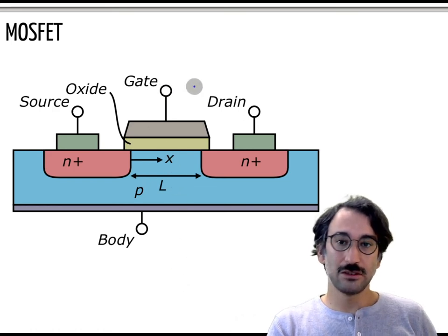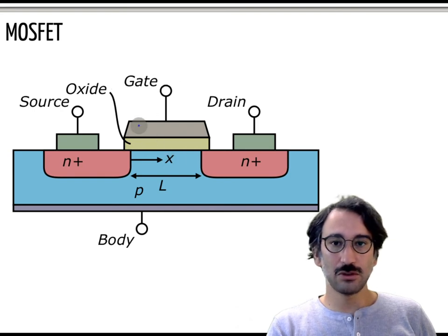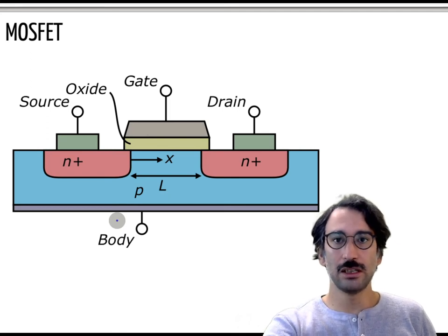So it is different to a thyristor. It is not a gate controlled, current controlled device, but it is voltage controlled. But of course, as we will discuss in the next slides, there is a capacitance between the gate and the main body, so you need to charge or discharge those capacitances to control the device.